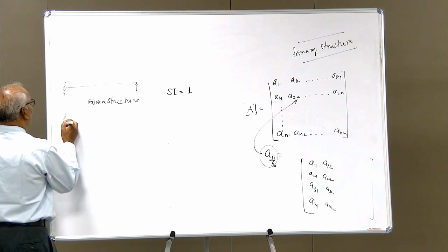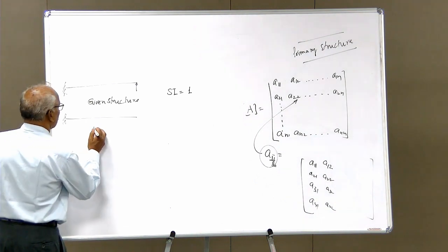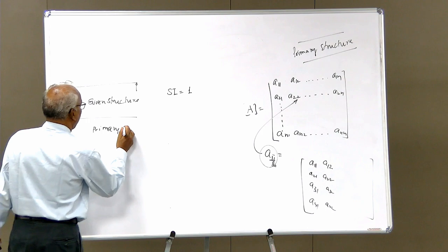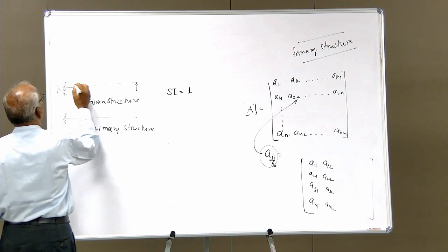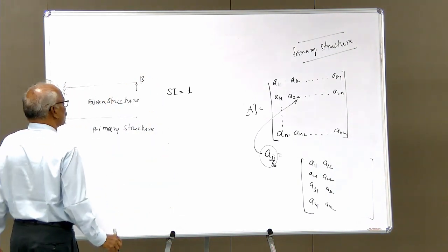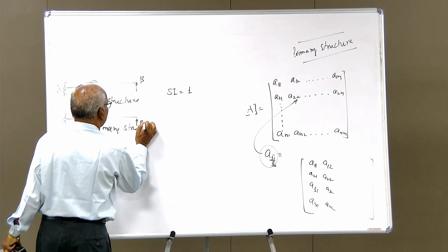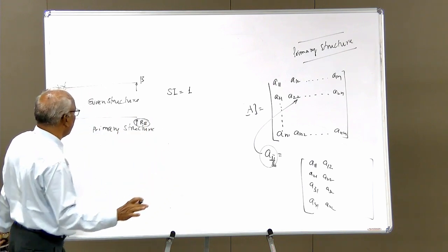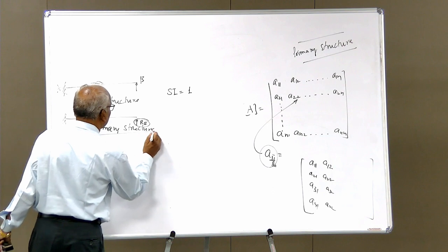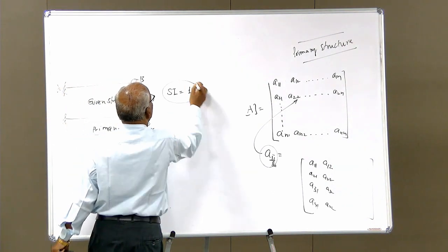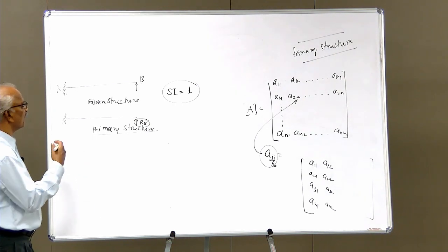Now, what we do is, you can just remove the right support and make the structure a primary structure. This is a primary structure. That is, you have removed the support at B. This is AB. So that means you have treated RB as redundant, removed RB, and the structure is now determinate. This is one way of making the structure a primary structure. Because the static indeterminacy is 1, you have to remove any one internal force, any force or reaction, so that the structure will become determinate.